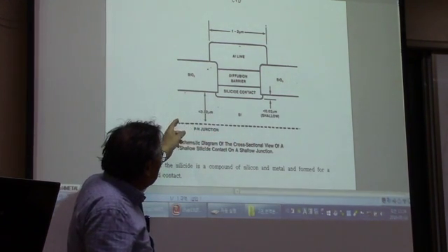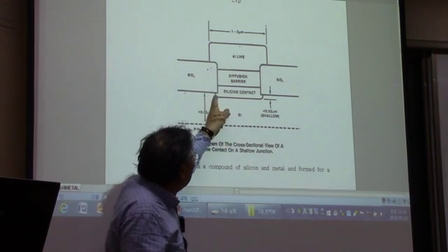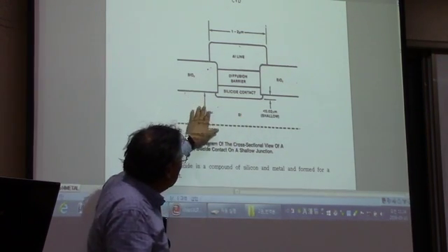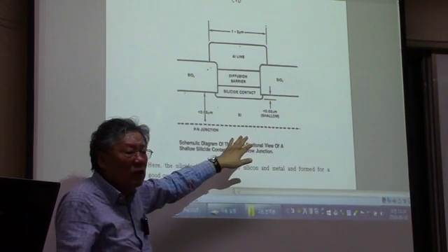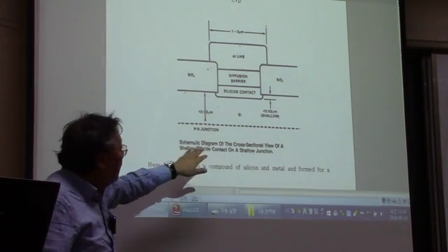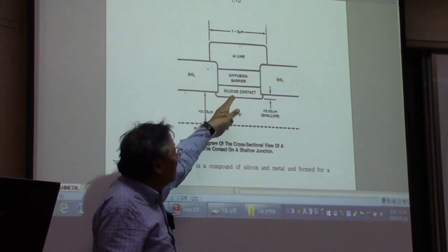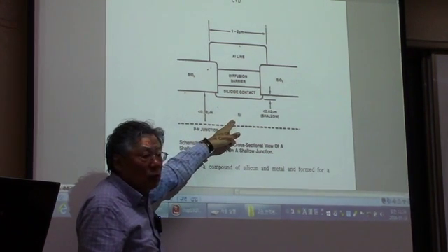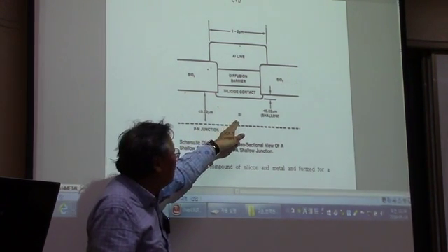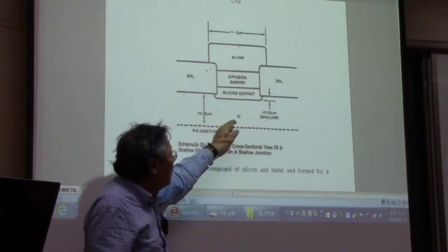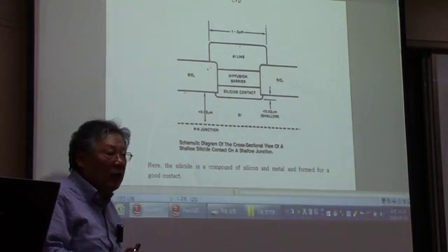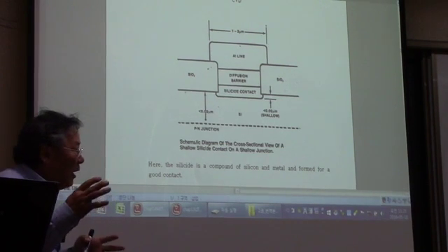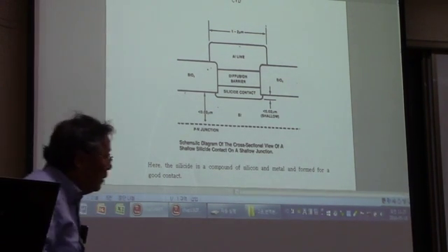And this is the silicon, and then this contact holes, usually this is the area with a heavily doped region, okay? Because this metal lines is going to have an input to the silicon substrate, so that if the contact area is not heavily doped, then we have to have a high resistance.